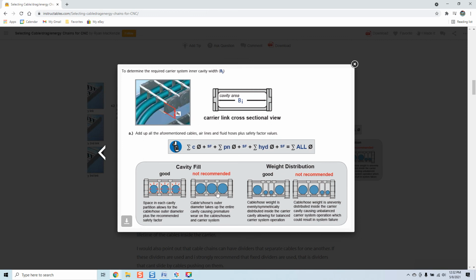If you confine them improperly, whether it be with minimal spacing where you see here, or if we had this cable chain overloaded with cables, we'll cover that later, you will get basically the same effect: massive amounts of friction and massive amounts of pull and push, especially when our axis move fore and aft on the Y, on the X. That's when you typically see that, and you see cable degradation.